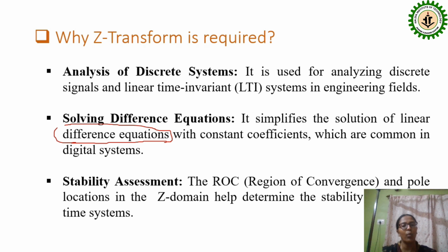To know that, at first you convert the signal into the Z transform, and then there is one property, the ROC property. ROC is the region of convergence, and in the region of convergence you can locate all the poles. The Z transform has a numerator and a denominator.